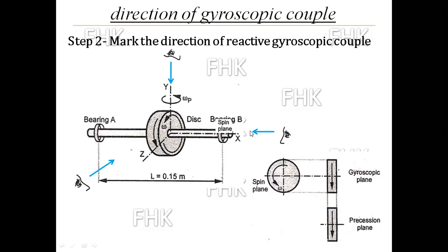So a right hand side view you will draw left of the front view, exactly left side of the front view. So this will be front view. So this will become a right hand side view. So this is front view, this is top view, and this will be the right hand side view, which you have drawn left to the front view.